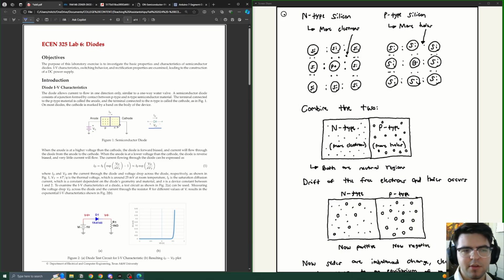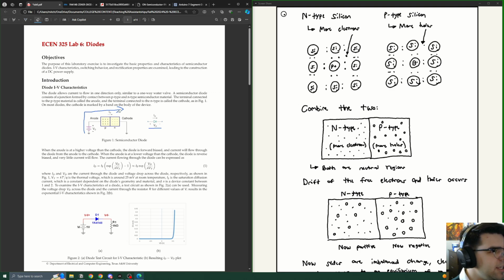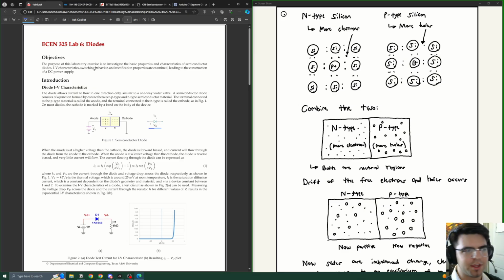Whenever we apply some sort of voltage across these, current is really the electrons themselves flowing. You're used to current flowing out of the positive terminal of the battery and then going to ground. Well, really, everything happens in the opposite direction. We knew this for a while, but we were already doing everything with the convention of current flowing from positive to negative, so we've stuck with that convention since then. But the electrons are what are actually flowing, and the holes can flow as well, where electrons move from the spot they're in, and effectively the hole can flow. But the electrons are much more mobile.